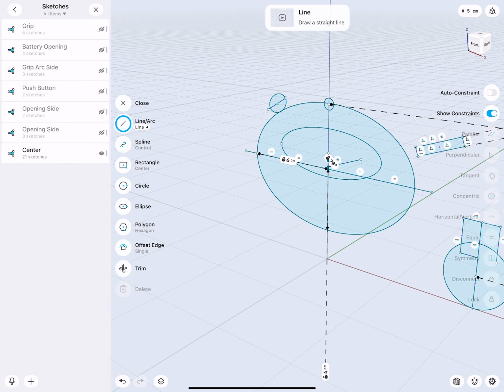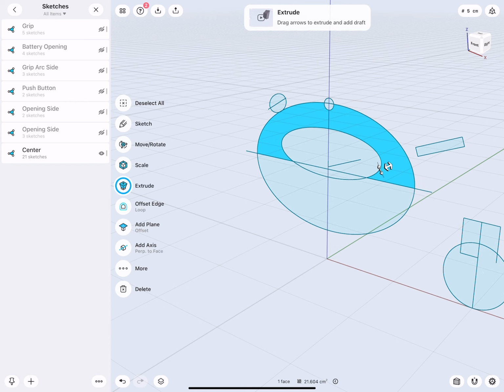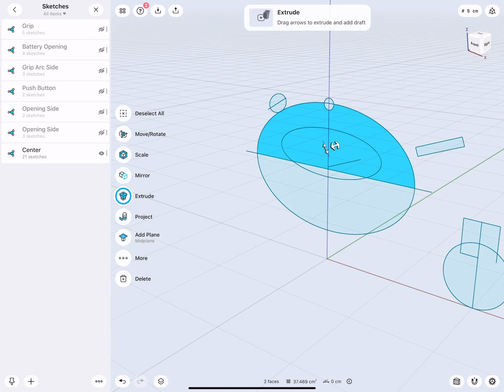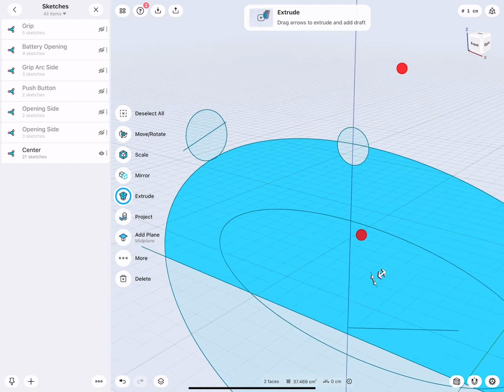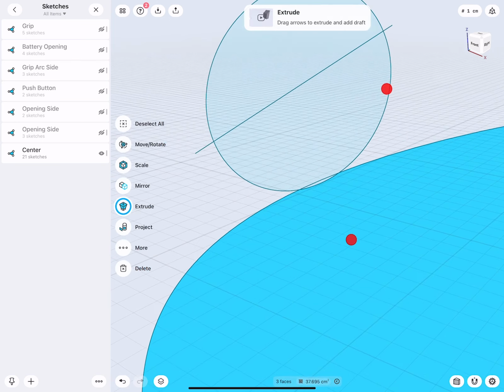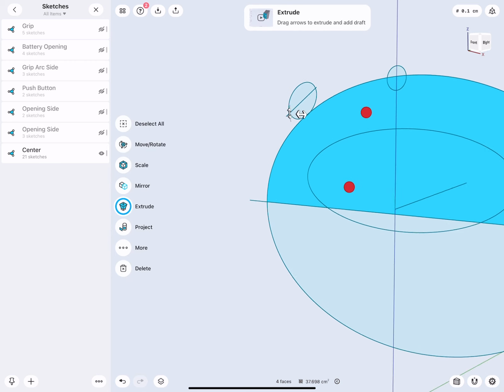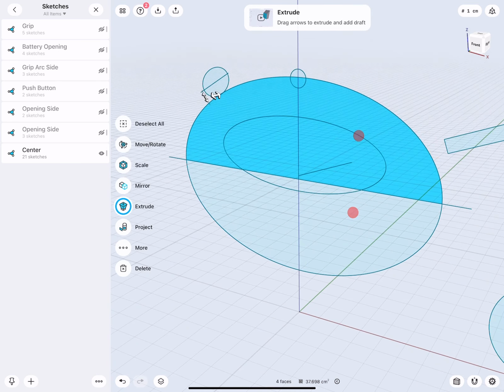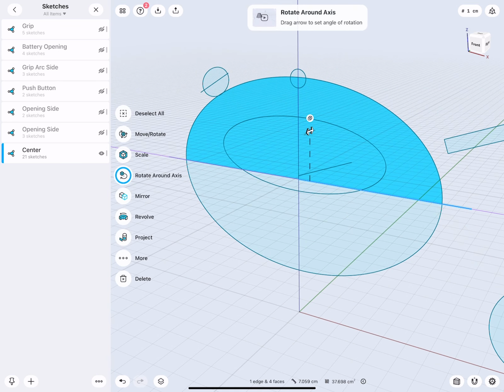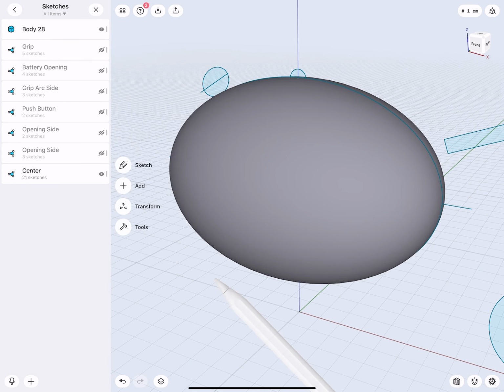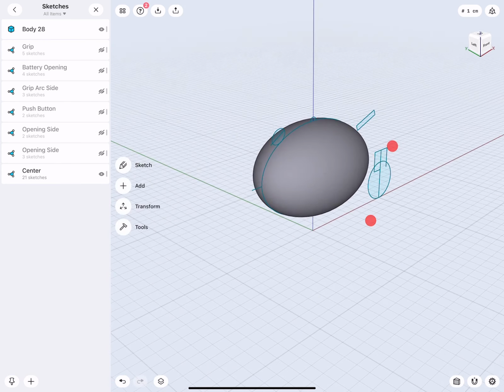And the sketch solver in Shaper automatically slices sketch profiles by the way lines intersect. You see, super easy. So all I have to do is make sure I select all the correct segments like this. Select my revolve axis and do a revolve. Very good. Cool.